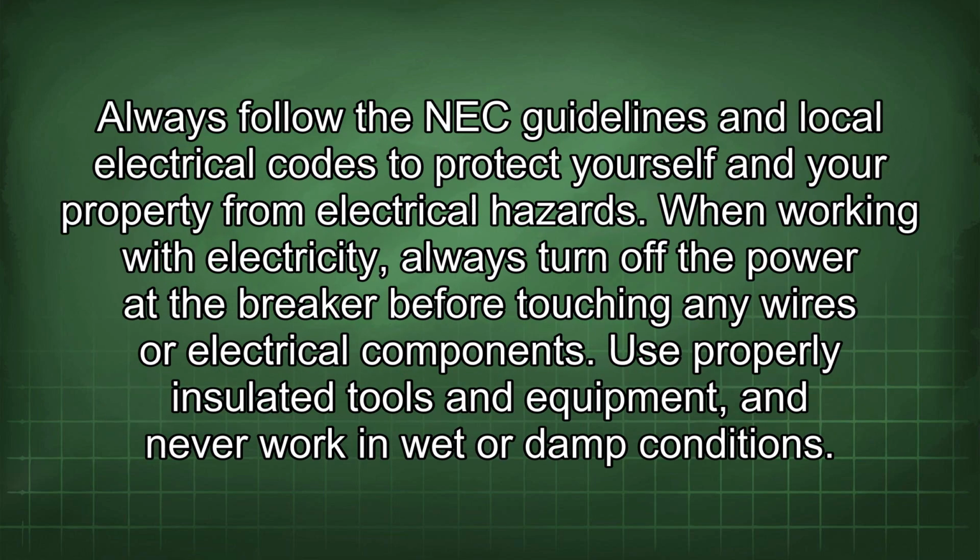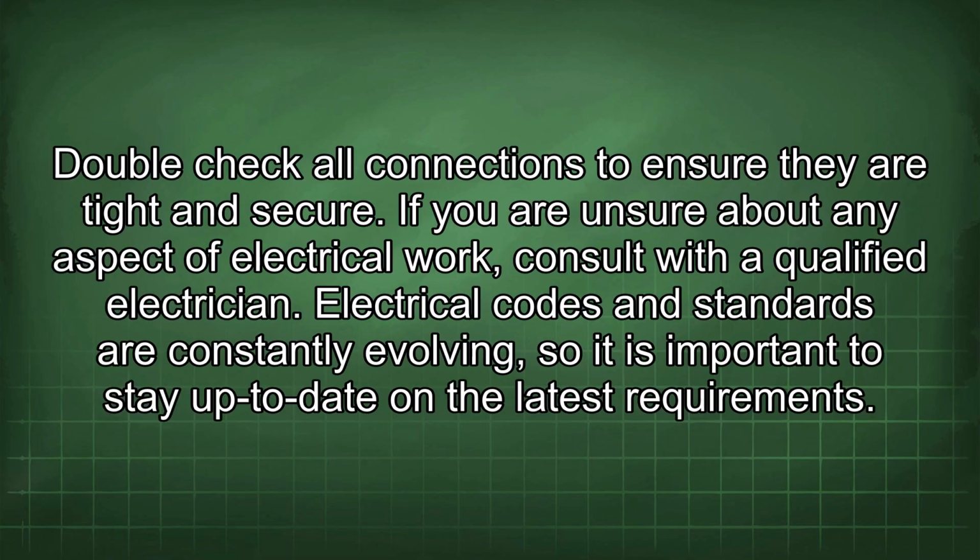Always follow the NEC guidelines and local electrical codes to protect yourself and your property from electrical hazards. When working with electricity, always turn off the power at the breaker before touching any wires or electrical components. Use properly insulated tools and equipment, and never work in wet or damp conditions. Double-check all connections to ensure they are tight and secure. If you are unsure about any aspect of electrical work, consult with a qualified electrician.